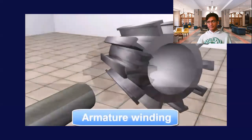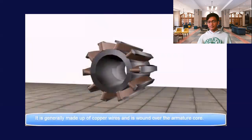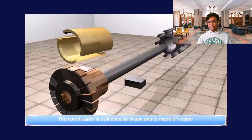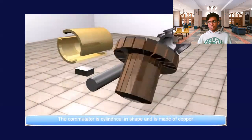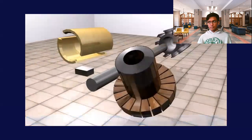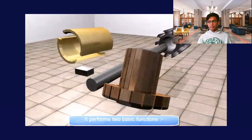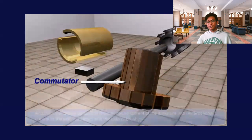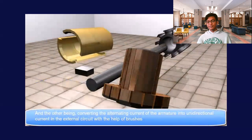Next is the armature winding. It is generally made up of copper wire. So you can see the brown one is the copper winding. Commutator. The commutator is cylindrical in shape and is made of copper. It performs two basic functions. One is collecting the current from the armature conductor, and the other is converting the alternating current of the armature into unidirectional current in the external circuit with the help of brushes.